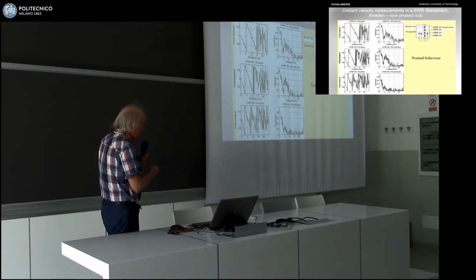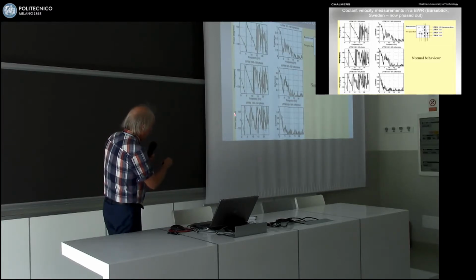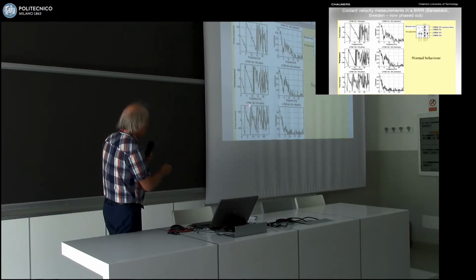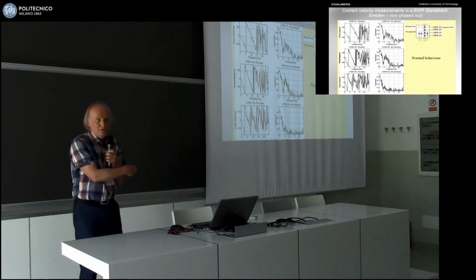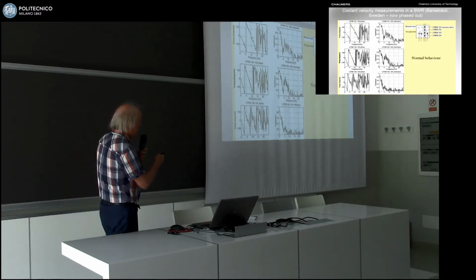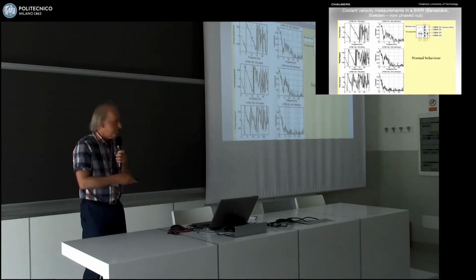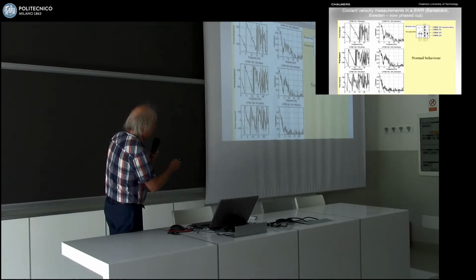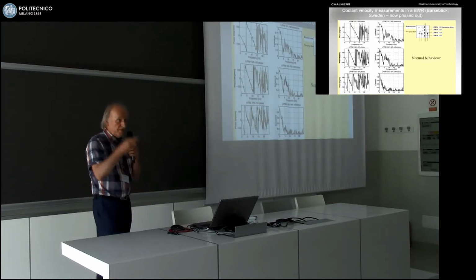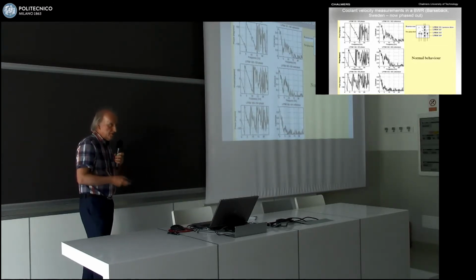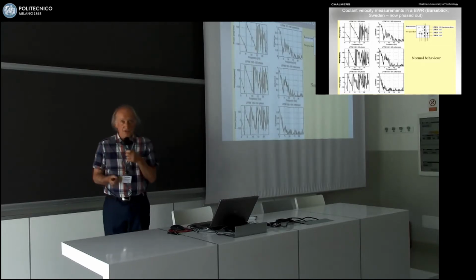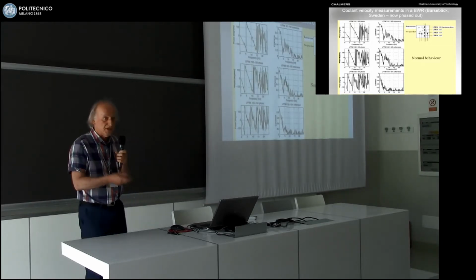Tau is the time delay, and this is the phase. Now it looks a bit messy here again, but basically that's a linear function. It's just that minus pi is the same as plus pi, so we fold it back so that you can plot it easier. So there is a linear phase up to a certain frequency, and you can see that here there is a larger value of the slope because it takes a longer time for the steam to pass between two lower detectors than up where the void fraction is bigger, so the velocity is also bigger. So one can measure the velocity, one can also find out if there is a deviation from the expected velocity.